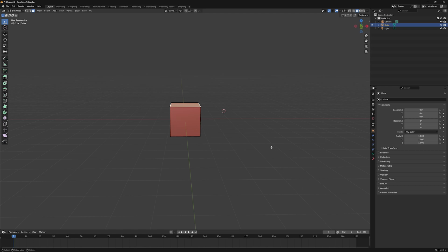With the top face of the cube selected and the pivot point set to median, we need to select the Shear tool from the toolbar. This creates the Shear tool's gizmo, which displays 3 short axis lines, though these may be difficult to see depending on the colors in the background.